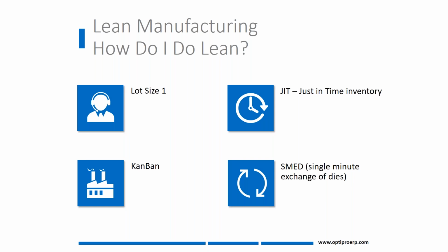SMED, single minute exchange of die, another Japanese concept. This speaks to specific manufacturing operations that require die changeovers, or tooling changeovers, or setups. And this is sitting down and understanding that if the press isn't banging, if the spindle's not turning, if we're not making chips, we're not producing value.